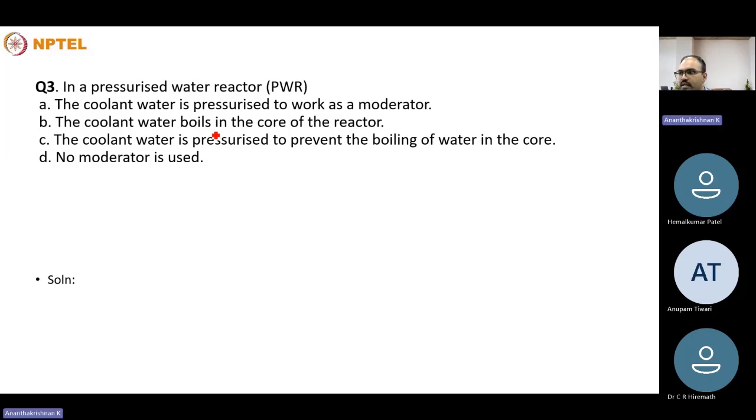A pressurized water reactor generates steam indirectly using two water circuits, a primary one and a secondary one, while the boiling water reactor produces steam directly using a single water circuit. Usually the nuclear reactors are used for steam generation and electricity production.